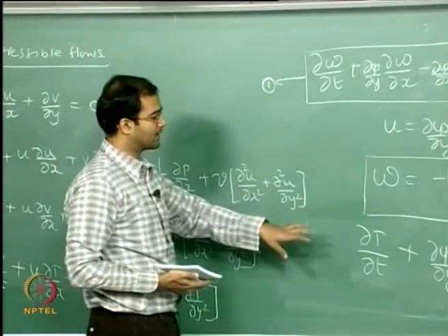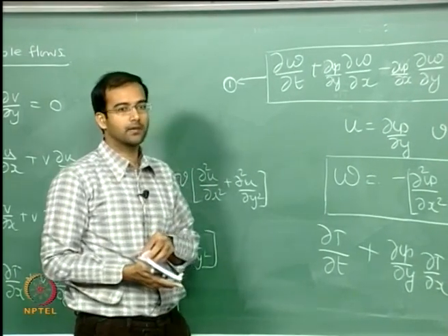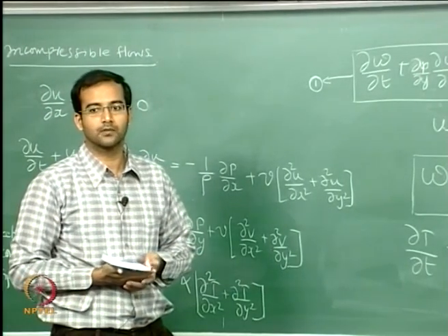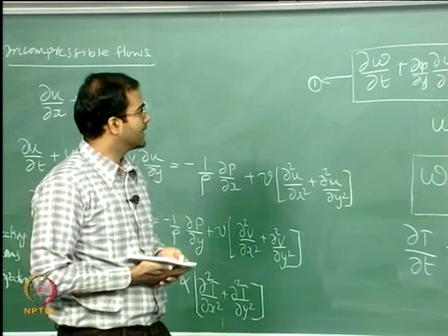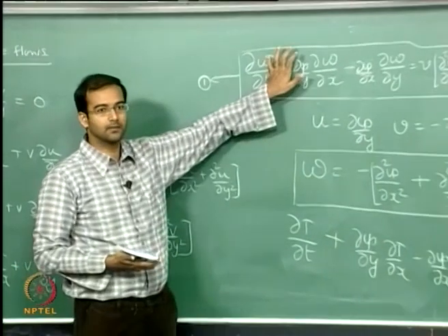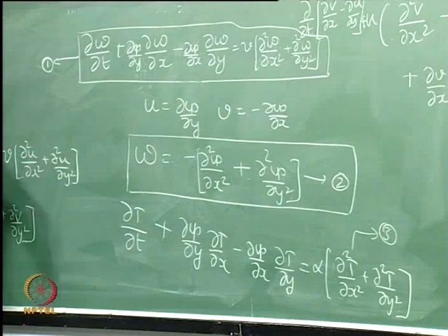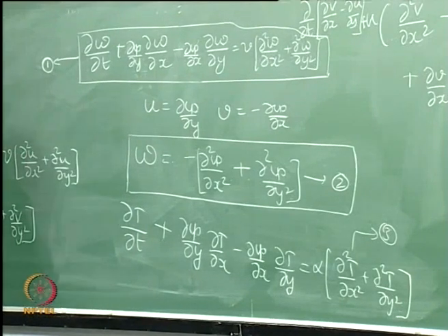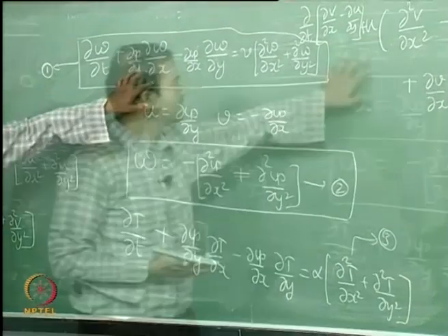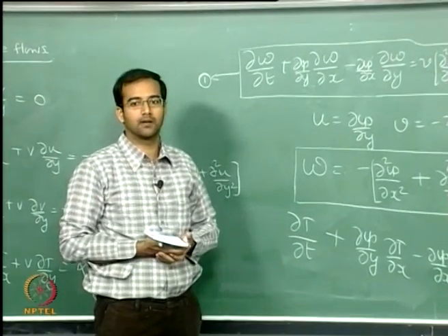So these are the equations that you exactly have to solve in your particular project, and I will be giving the papers. You have to apply the corresponding boundary conditions to solve this problem. So for a particular problem you have to do it, and then you can probably look at the steady state solution where you don't have to consider the time derivative, only the spatial derivative, and you can do this iteratively. There are a couple of techniques like Gauss-Seidel or Gauss-Jacobi iterative techniques which you can use, and you can use simple finite difference methods to discretize these derivative terms.